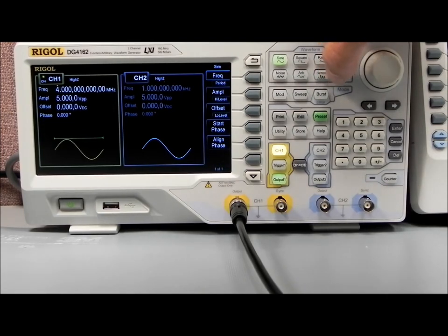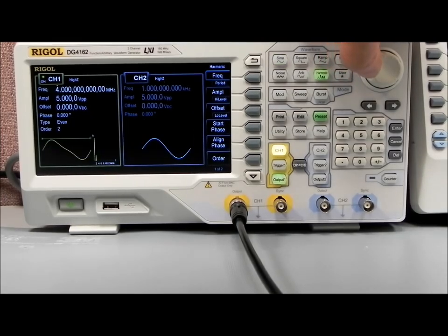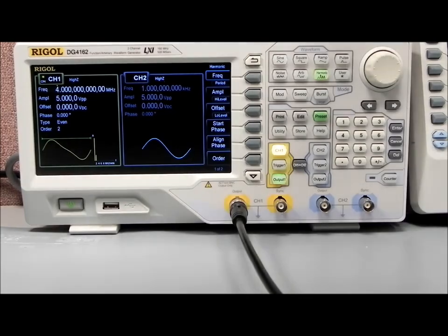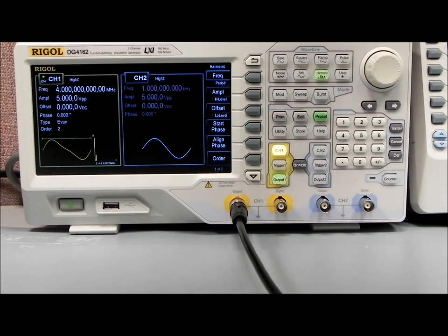I'd like to go into the harmonics just a bit. A colleague of mine put together another video that deals more with the harmonics, but with the harmonics you can create, using Fourier coefficients, particular waveforms. You can add odd harmonics as an example to create a square wave, which can be useful in education as well as doing some harmonic testing for filters and the like. Again, that's just a pretty quick run through.